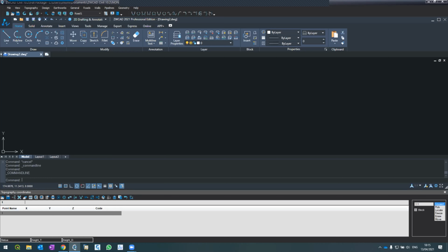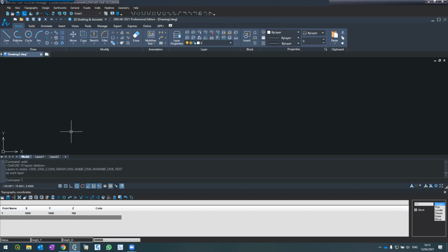We enter the point name, the easting, the northing, and the Z. We also learned that whenever we make a change in the coordinates list and we hit the refresh button, which is upper left here, the system scans the list and updates our drawing accordingly.